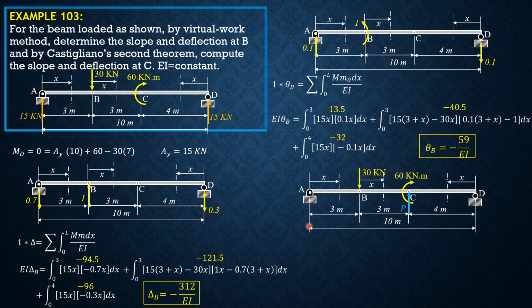So remember, due to the actual loads, the reaction here was 15 kilonewtons upward. Then let's just concentrate on P. So the reaction here, which is downward, times 10 equals P times 4. So P times 4 over 10 is 0.4. Therefore, this is 15 minus 0.4P.